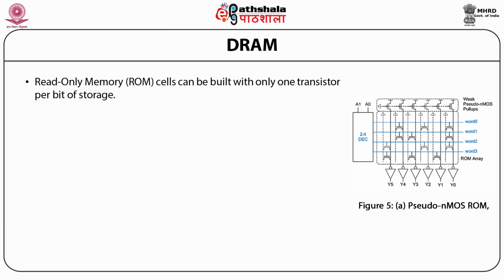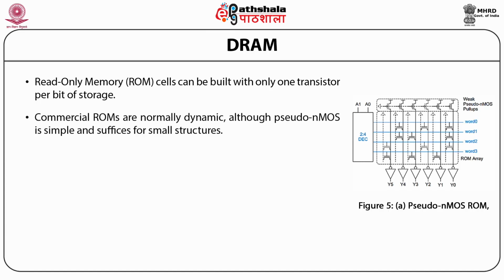A ROM array is commonly implemented as a single-ended NOR array. Commercial ROMs are normally dynamic, although pseudo-NMOS is simple and suffices for small structures.